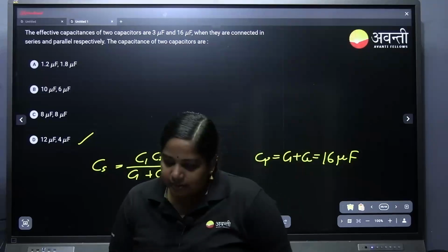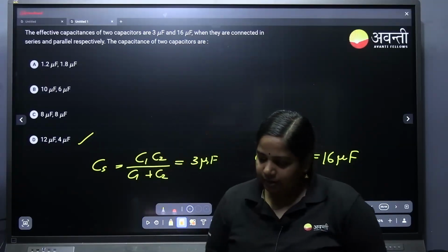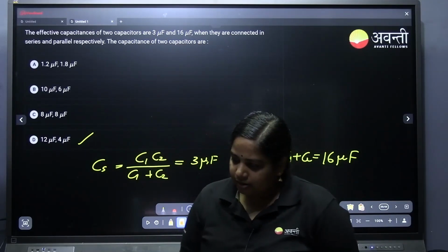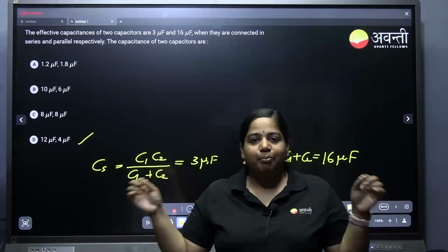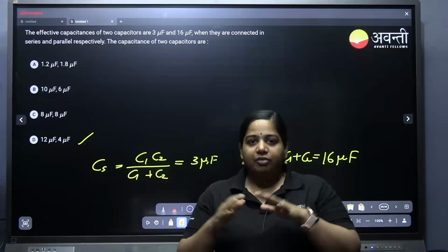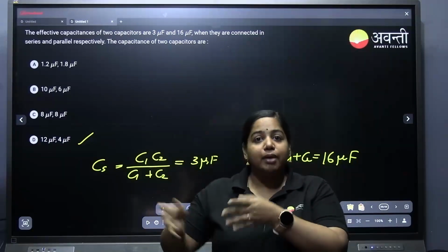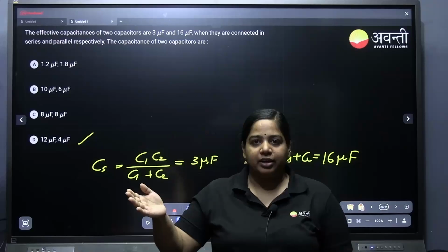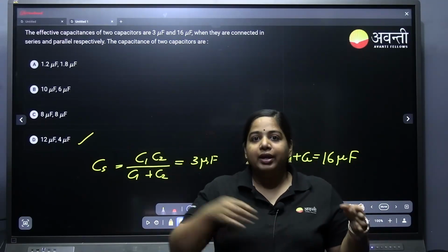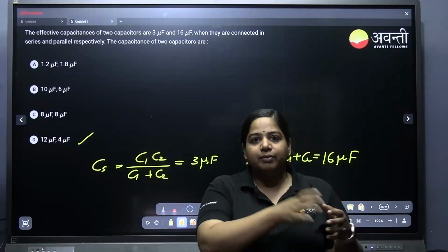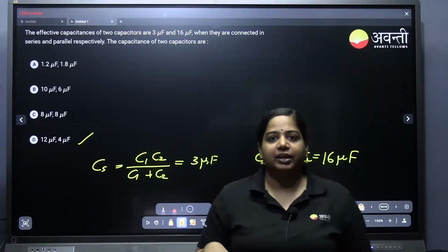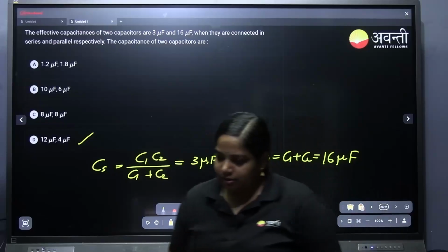Surabhi, did you understand? Like total potential we are applying is 1000 volt. If one capacitor can maximum withstand 300, if I am keeping 4, it will split equally. Like one will have 250 volt only, less than 300. That is fine. Now you understood?